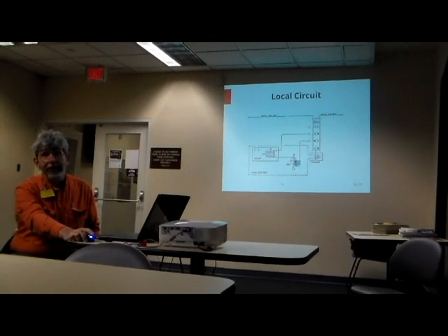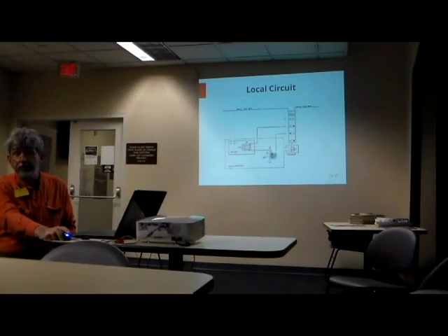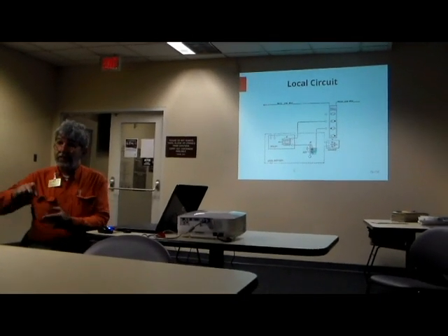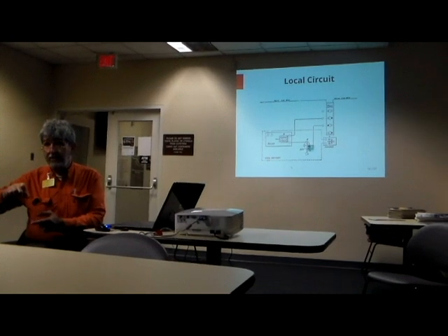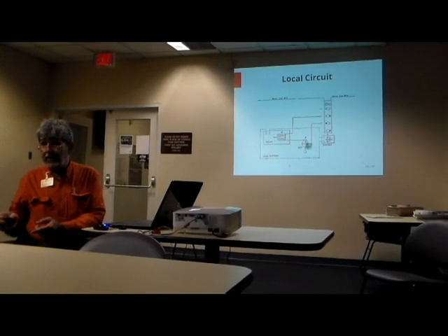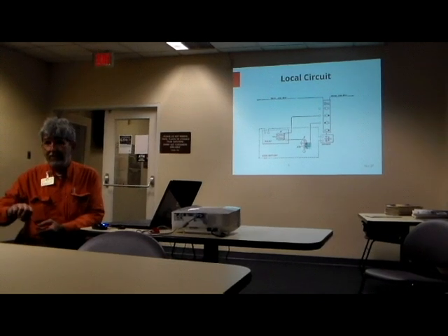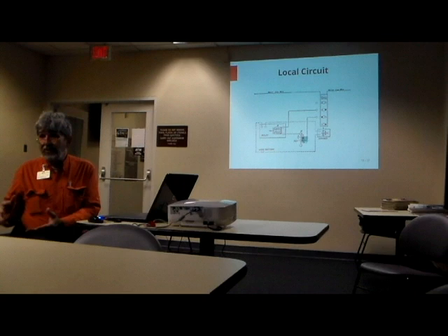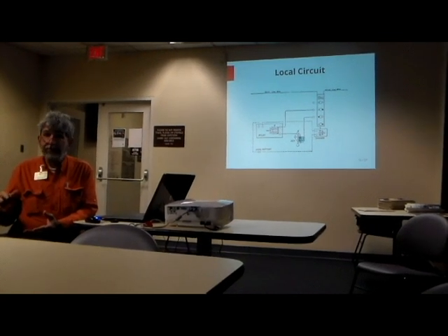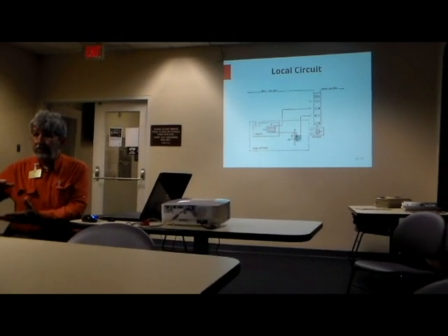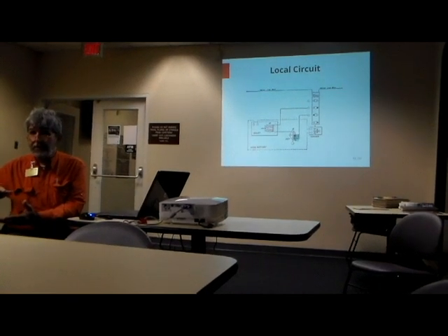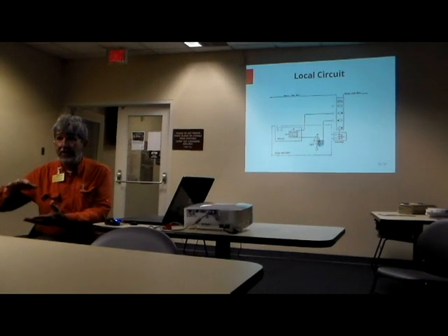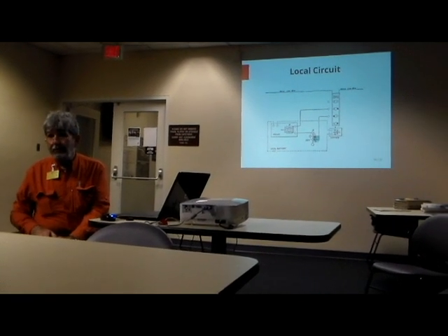Now, the nice thing about the gravity battery, the reason it continued in service so long, was that it was so easy to service, since the two fluids divided themselves by their specific gravity. When you'd run down, you'd add a little more water and a lot more of the vitriol, and bingo, you'd have a full battery. After about a day, the gravity separation of the two fluids would occur between the blue vitriol and the water, in the area where the zinc is, and the battery would again be producing